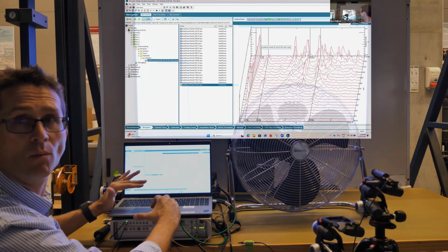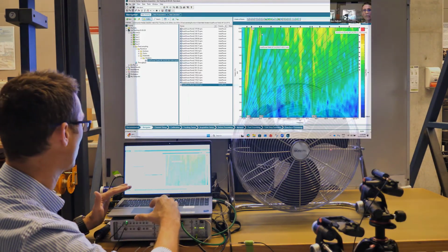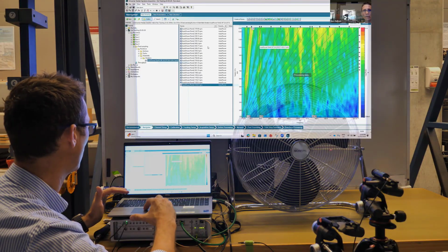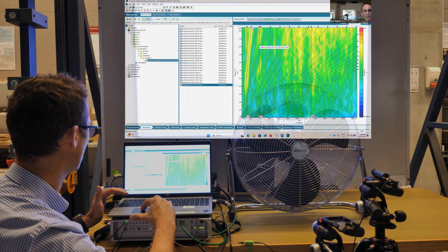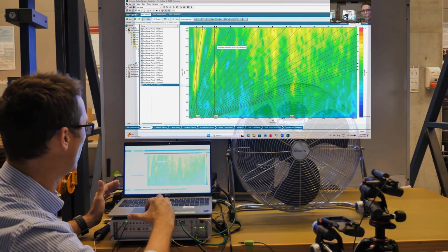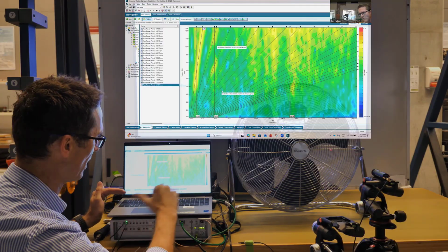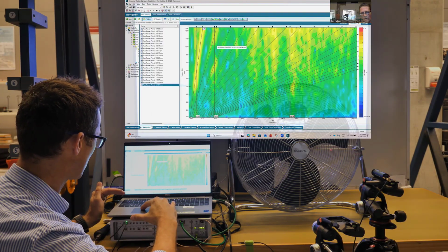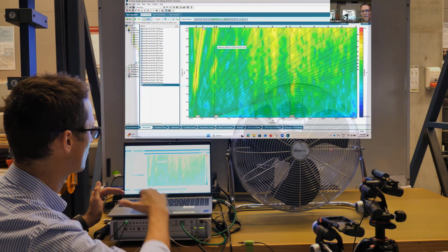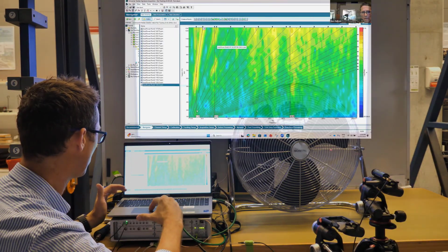It's not a brilliant way to review these data on a waterfall plot. It's quite a historical way to review them. Nowadays, with the extra computational horsepower we've got available to us, a colour map or Campbell diagram is a more meaningful way to present these data. And now we're essentially looking down from above on those spectral data. And so we've got spectra here at 100, 150, 200, 250, etc. It interpolates between them for the sake of colouring in the colour map.